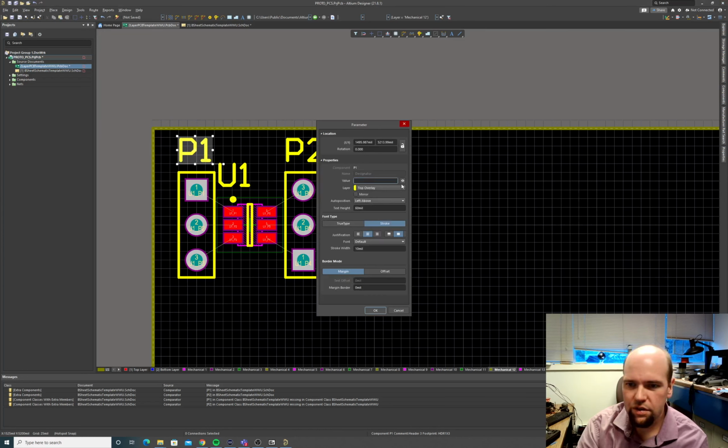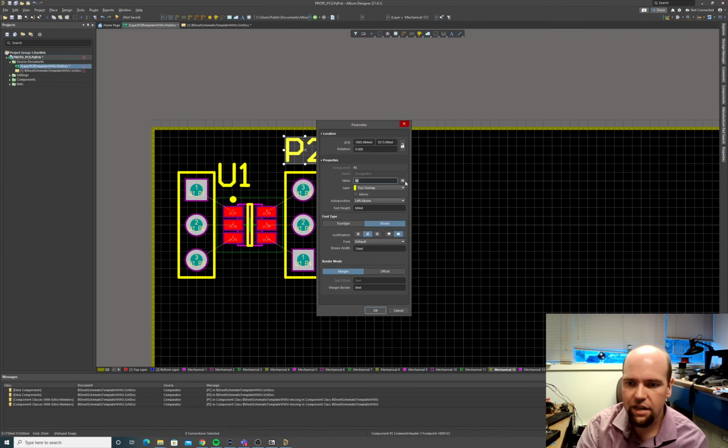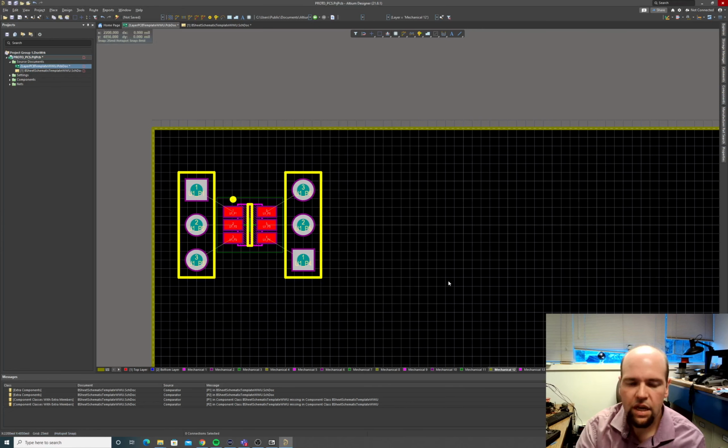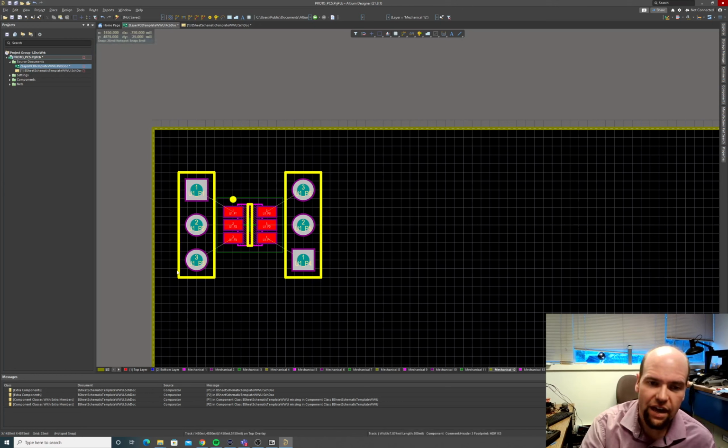Oops. So you can just hide it like that. Double click it, hide the designator. Double click it, hide the designator. But what you might want to do is, for your own benefit, label this thing. A lot of times labeling it on the back is still useful, so that's probably a good idea. You want to make sure pin 1 is indicated one way or another. So right now we have a pin 1 indicator on the part. It might be good to also add one to the headers here.